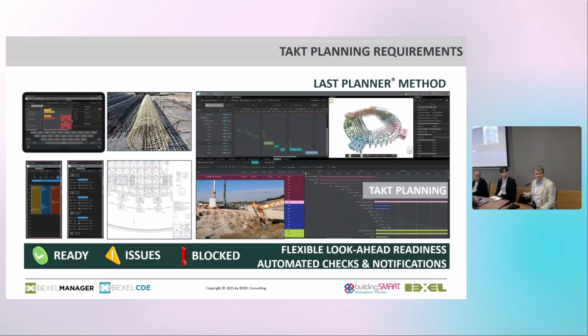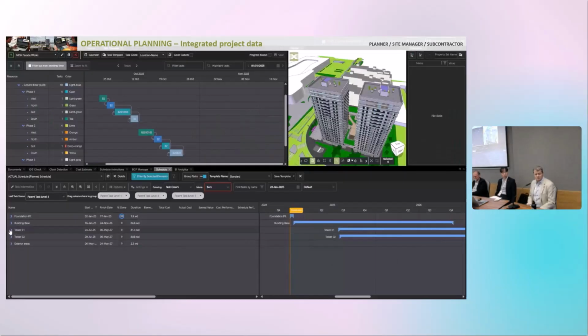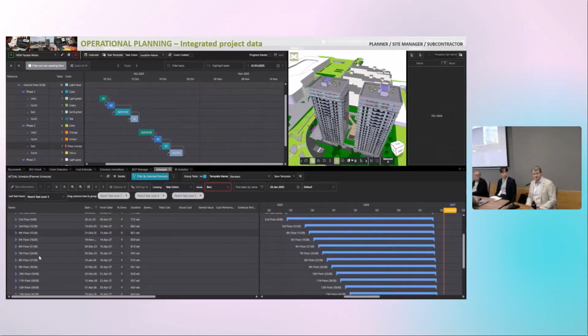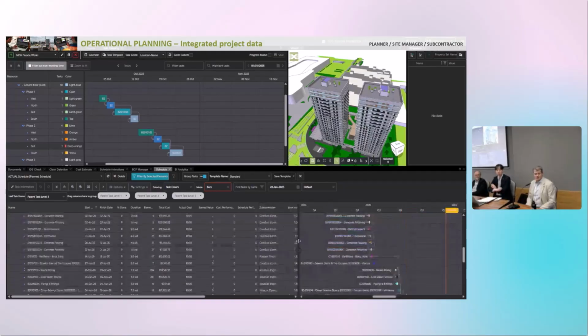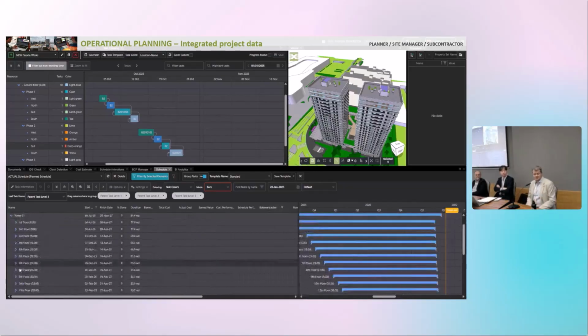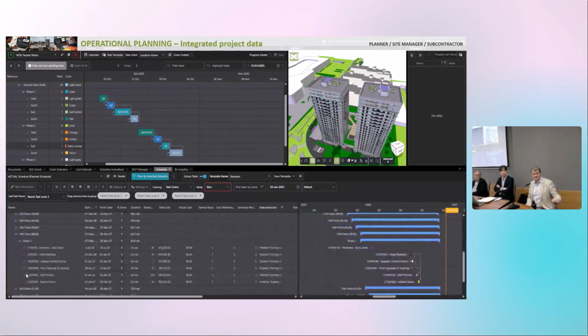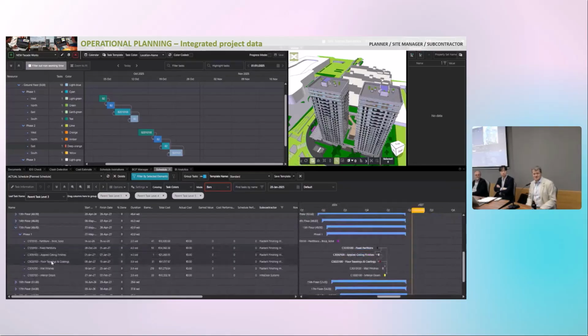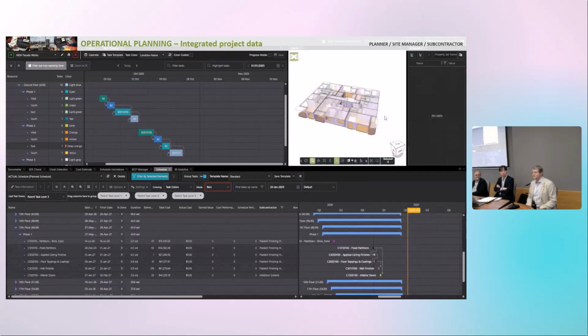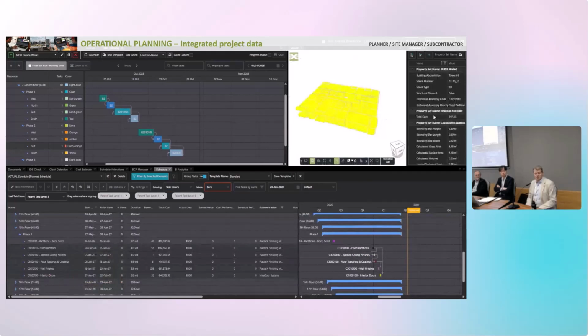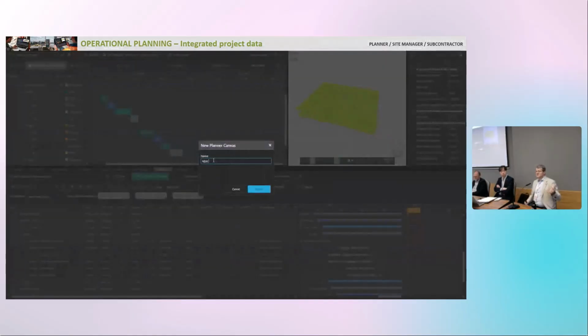So you will see all this. It starts from a Gantt chart which has all resources and quantities connected automatically with the BIM model, everything done automatically, not manually. Then you select some tasks for a certain subcontractor, and you see all these tasks are there. But now a single task for the entire floor, he will split to the apartments.